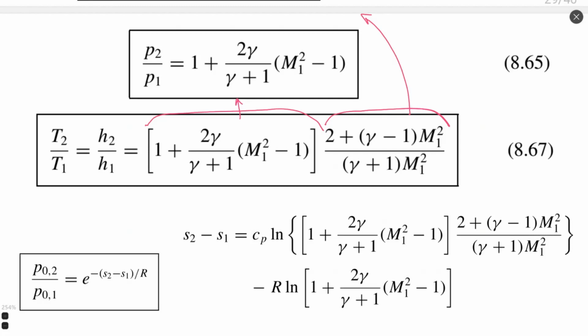But okay, this is absolutely no problem, to take the reverse value from this relation. You will see that in appendix B, which we will use as a reference to calculate normal shock waves. We have a reverse relation, not P02 by P01, but P01 divided by P02.